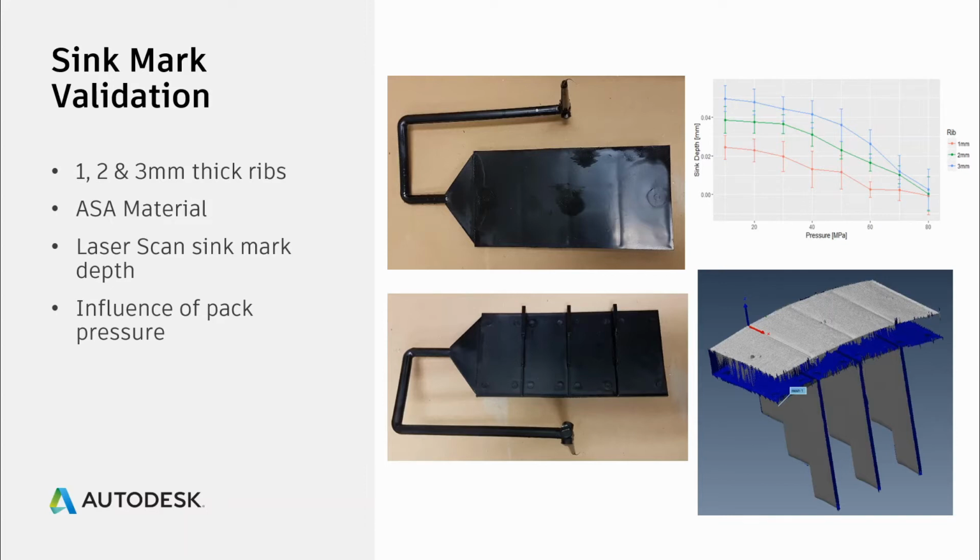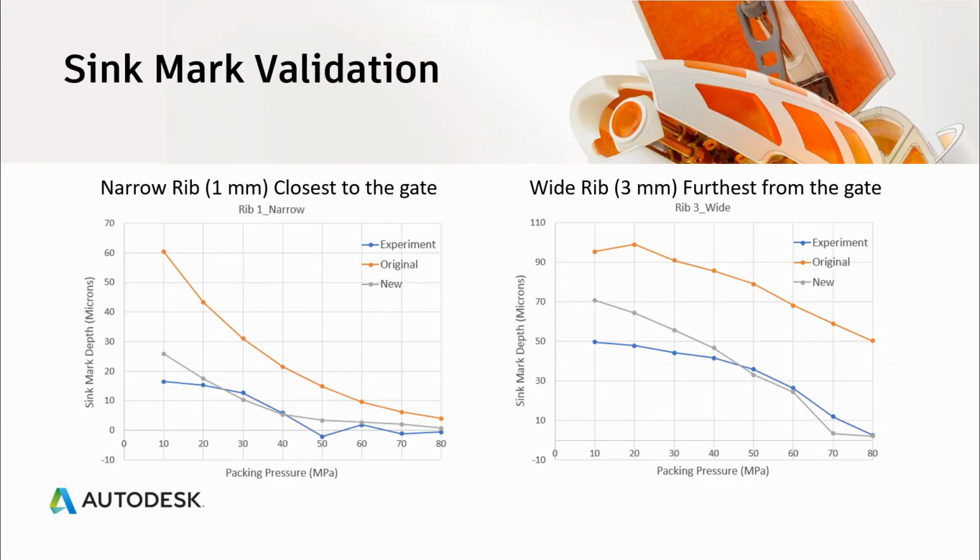And we've taken a laser scan of the sink mark's depth. And moldings and samples were collected for a range of different packing pressures all the way up to 80 megapascals, so that we could see the influence of packing pressure on reducing sink mark depth. So here's a comparison of those measured sink mark depths and the predictions.